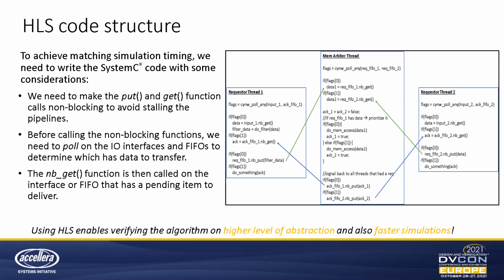This picture shows the pseudocode of the 3 threads or loops with the non-blocking communication. So the functionality here is unchanged, only the coding style changed a bit. And this way, we start a new loop iteration on each new cycle, even in the behavioral SystemC simulation. So we can do a new IO input handshake on every new cycle in SystemC simulation, just like in pipelined RTL.